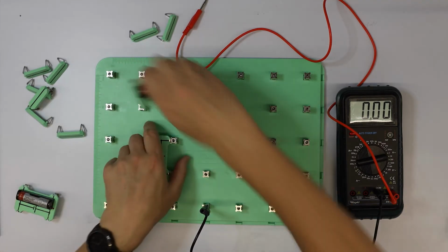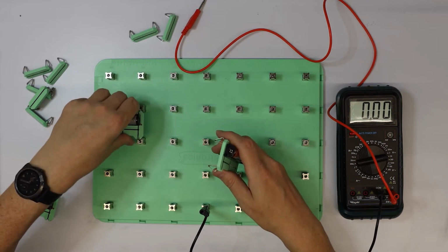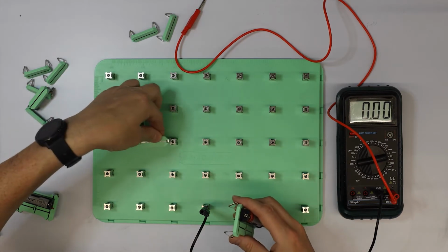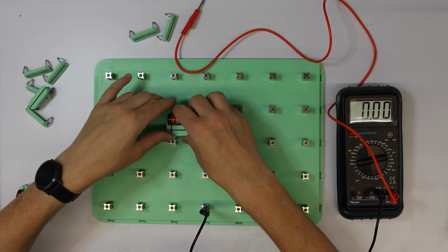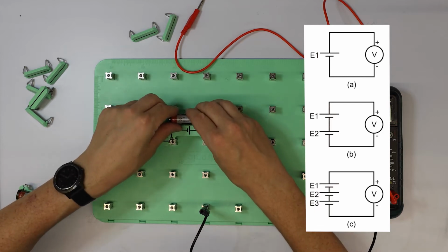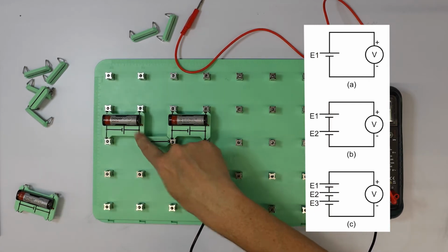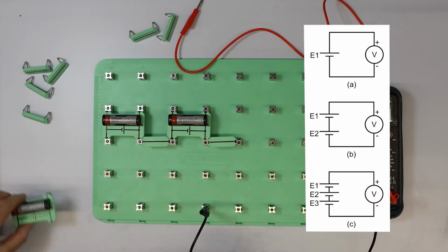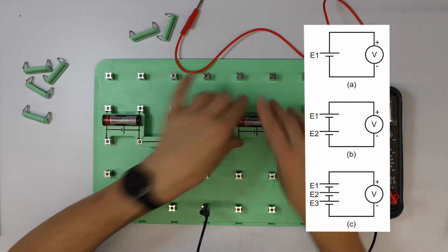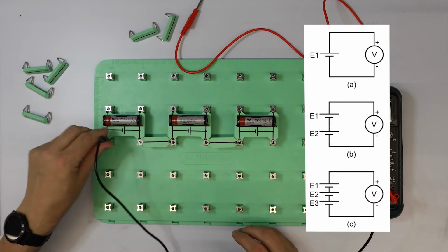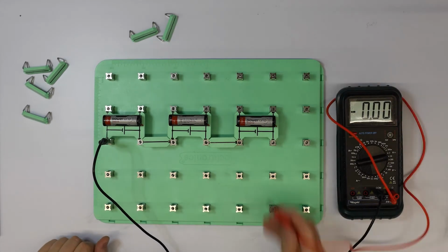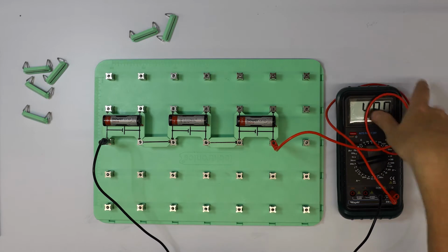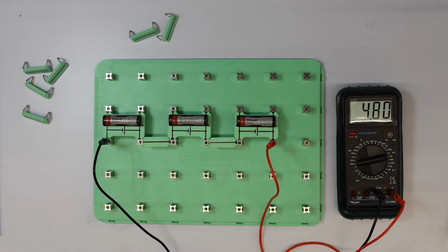I'm going to need to go a long ways on the board to fit everything in, but if I put my first battery there, just one linking thing, I don't actually need 2 in this case. Connect my second battery. So here I've connected the positive terminal of one to the negative terminal of the other one. And I'll put my final battery in the series in at the end here. And I'm going to measure from the negative end of the line of batteries here to the positive end of the line of batteries there. Just move the cable out of the way. And as expected, we're getting a reading of 4.8 volts across the lot. So it's as we'd expect.